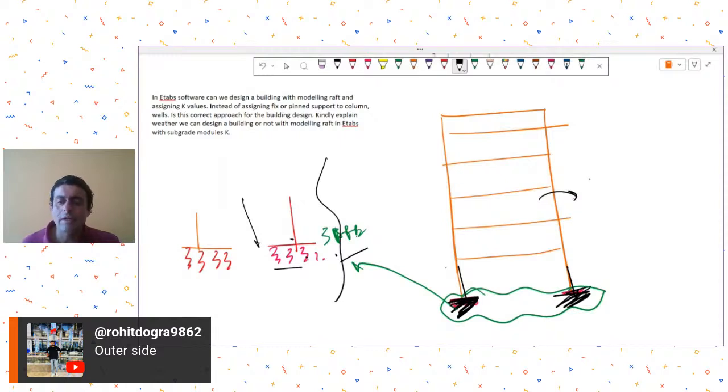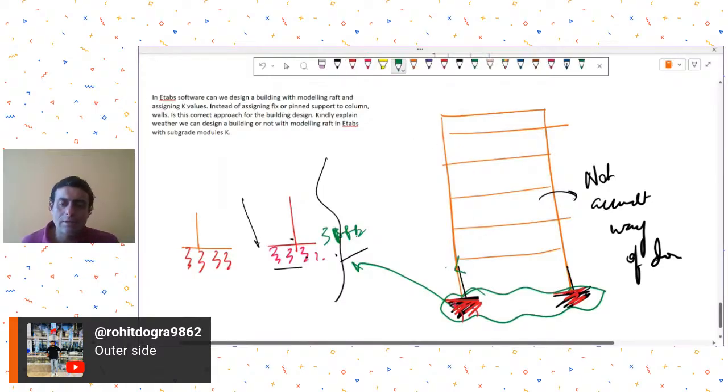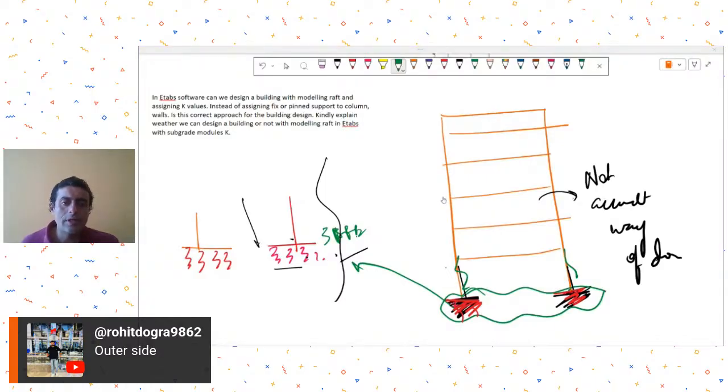then what we are doing in ETABS is not very accurate. So that means you should be assigning the spring stiffness in ETABS itself, because the spring supports may affect your analysis results in your vertical members mainly. Understood? Especially for the column effective length change.